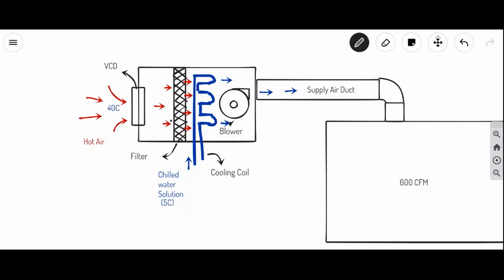Made by fabricator. So ducts are made by the GI sheet. We can fold it and make into the desired shape and size. Ducts are made with GI or aluminium, right? Yes, stainless steel, sometimes SS also. In the food industry, we use SS duct also.